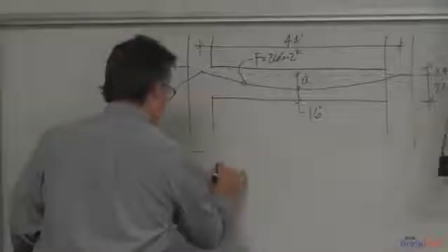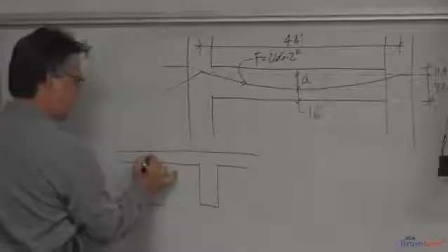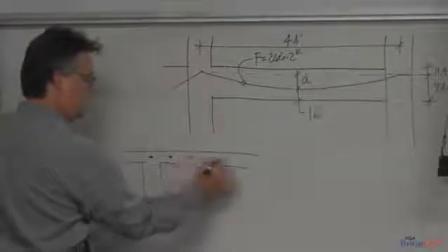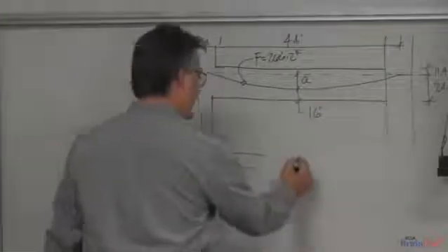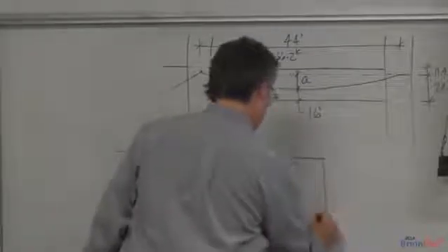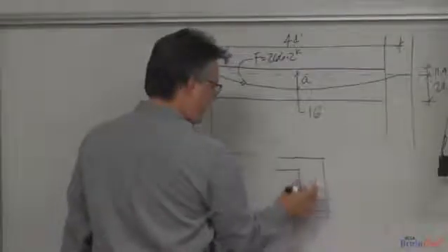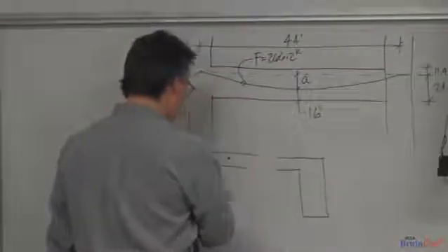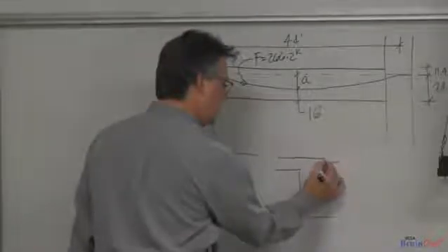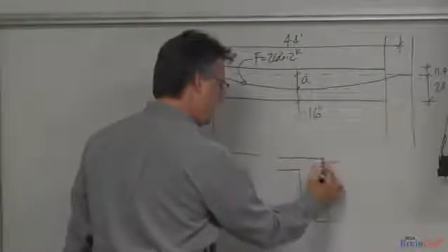And the biggest trouble that people have, I think I told you before, are slabs on ground, where the tendons actually do get anchored much higher than the centroid of the concrete, and they tend to twist. This has been the cause of lawsuits, that a slab on ground, you know, in plan has some deep ribs in it. Because they can only anchor the tendons up at the top, they put the tendons just in the slab. But what happens is, in a section, with the section properties, you know, center of gravity being down here and the force being up here, this tends to rotate.